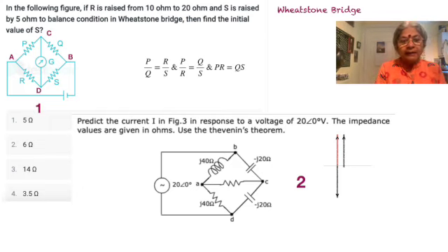So we see that J40 by J40 on the left hand side, the inductances, gives a ratio of 1, which is the same as minus J20 by minus J20. So definitely there is a Wheatstone bridge, and so there is a resistor connected across the diametrically opposite terminals, that is A and C, and so no currents flow. So let's have a look at the problem, because this problem was taken from a 5-mark question where the detailed solution needs to be given.